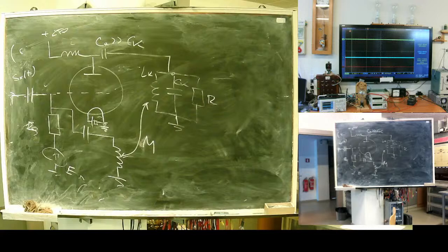Can you tell me? This one: input filters to suppress the Nyquist frequency, protective diodes. This one, digital? No, it's not an ADC. This one is the multiplexer, channel selector. This one is a controlled amplifier. It's an extension of the ADC array here. This one is the ADC. You said something like digital last time. I forgot. It's an analog to digital converter.